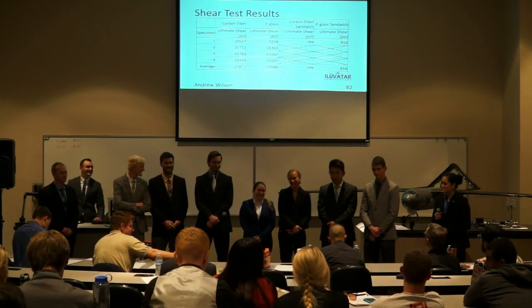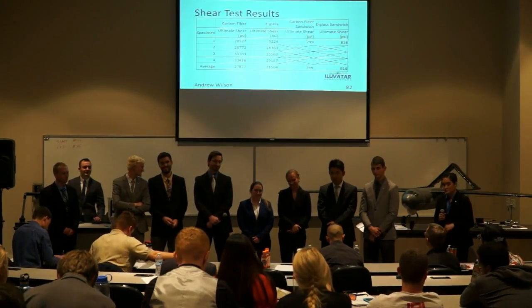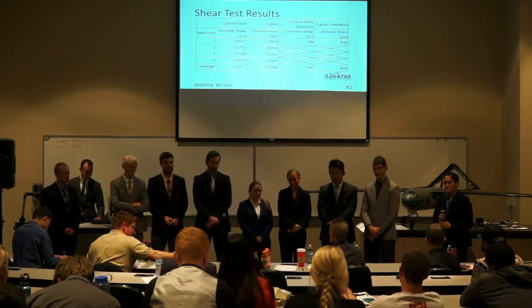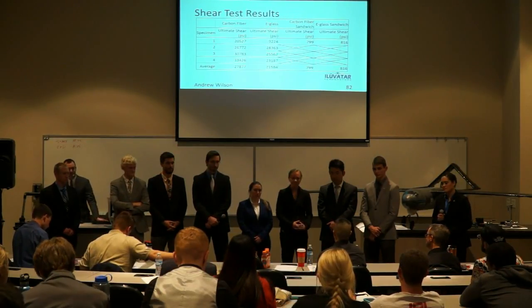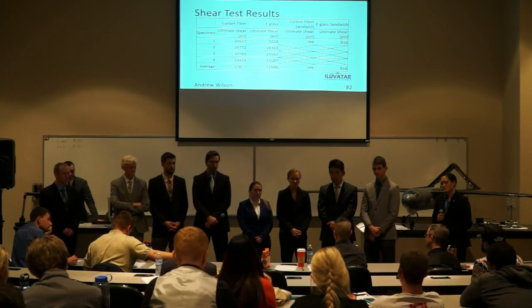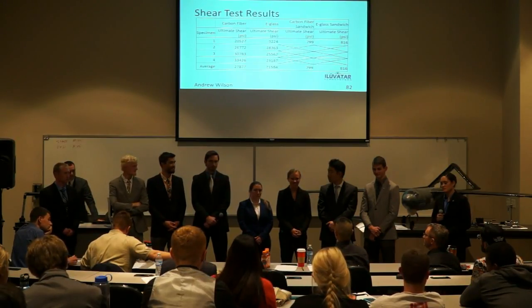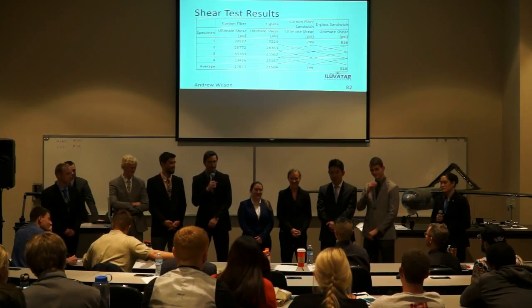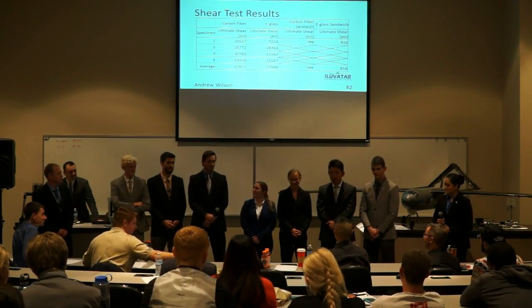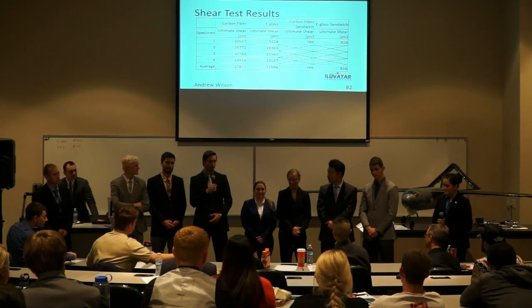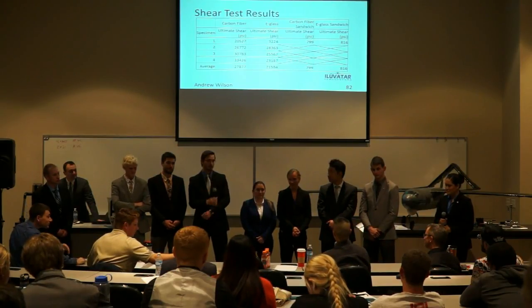Second question, going back on the structures fab side. When you guys sized up the thickness of your ribs, you came out to something around 3/1000ths of an inch. Have you guys looked at what 3/1000ths of an inch really looks like? With the micrometer? Does that number seem realistic in terms of a fab standpoint? No, that's why I went with the 2 layers of carbon fiber averaging 0.025 inches.